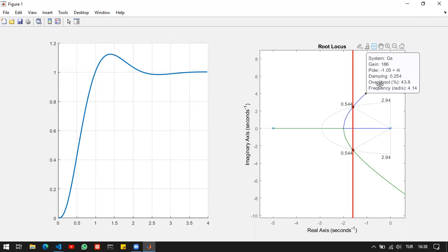So hope that you get the idea that if I look at the poles, if I look at the S grid, the S domain here, all I have to do is get to know zeta and omega n, their meaning, and how if I change that, the root locus changes, and suddenly I can analyze the system a little bit better. And if I'm going to be a designer, then this is crucial, because if I can comment on the system, the more I can, the better I can design my controller.